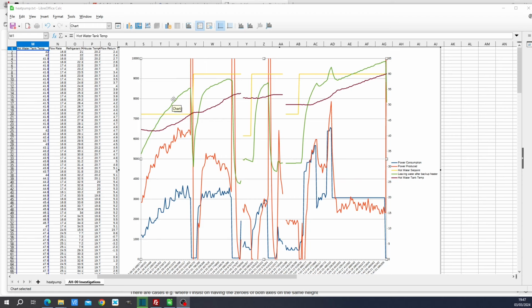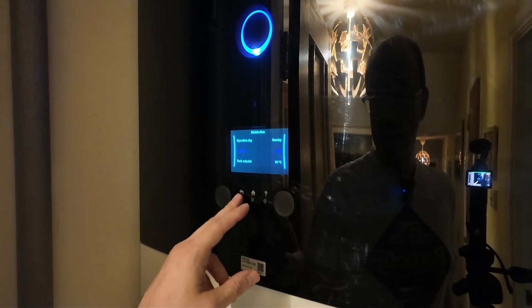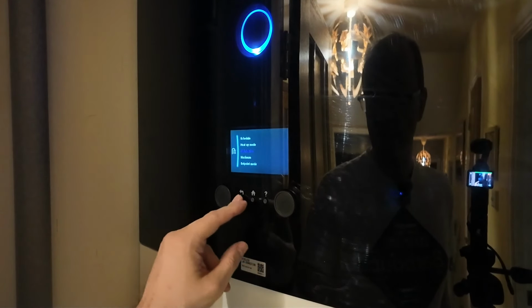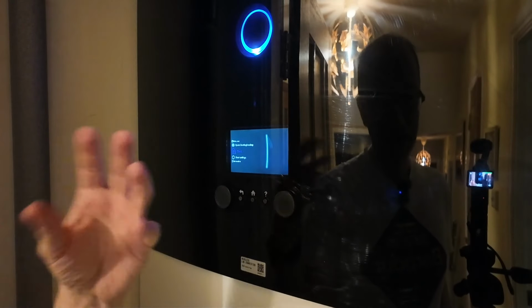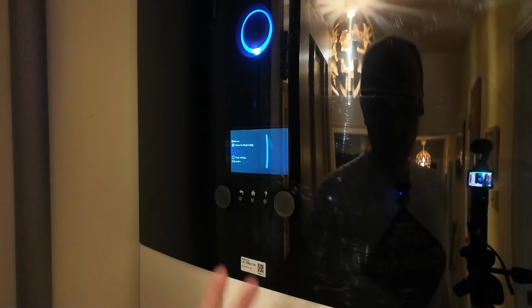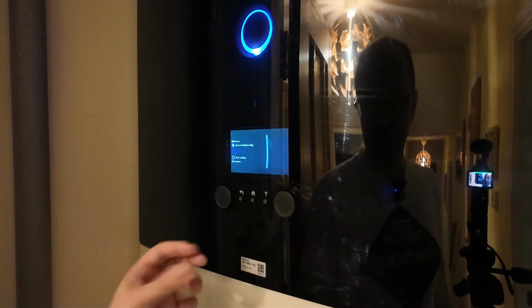This green line here shows you the actual flow temperature of the heating medium in the coil. So that's reaching 60 degrees Celsius here. It's not quite reaching 60 degrees Celsius here. After seeing that it had failed one more time, I went back into the settings, and this time I had this idea that maybe when the temperature of the hot water is required to go above a certain temperature, it requires a backup heater.